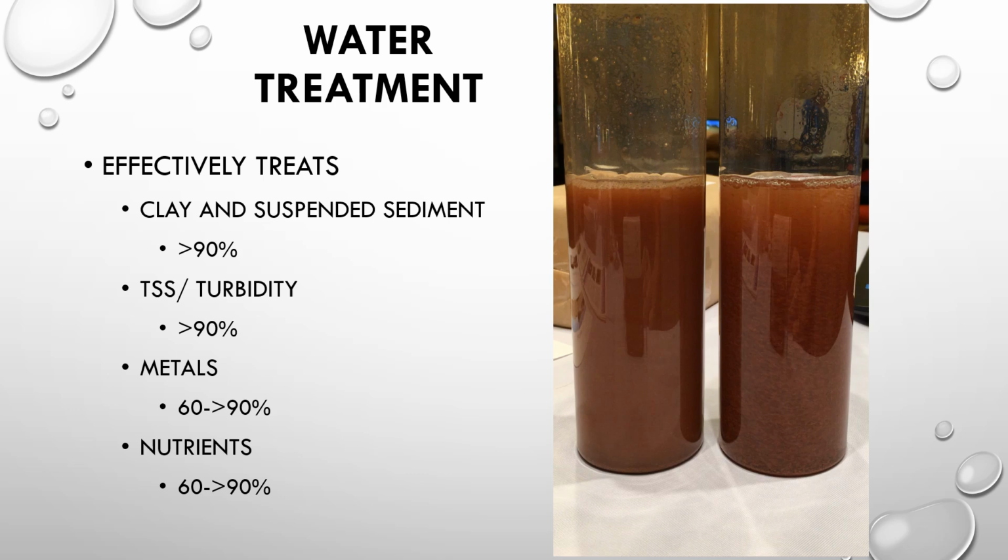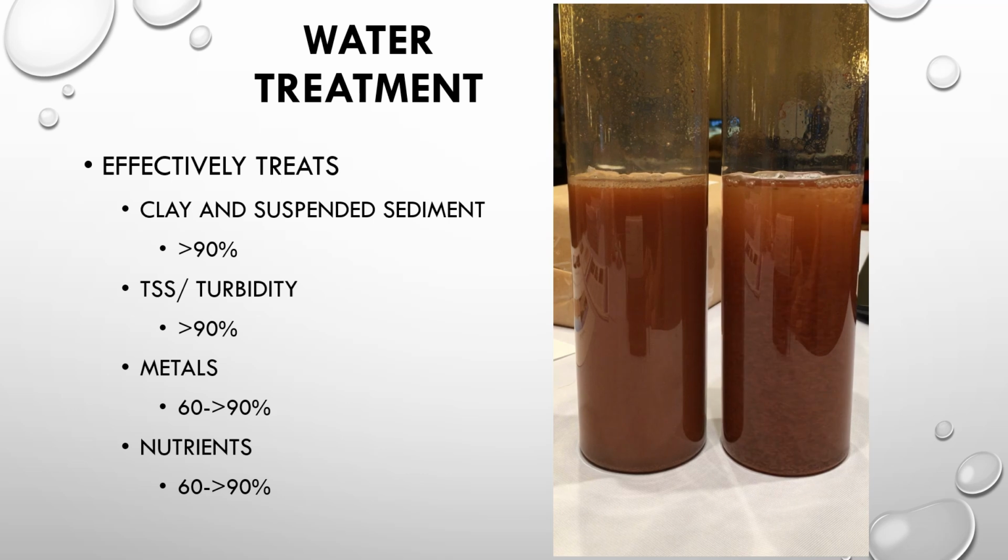What we'll typically see, if we're following the main rules for using these flocculants, which we're about to dive into here, is that we like to target around 20 NTUs after we've done a treatment, and that usually is in the 90 to 95+% removal efficiency for turbidity and TSS. If we use the right material and we use it in the right ways, it's very, very doable to achieve those types of removal efficiencies with these PAMs.